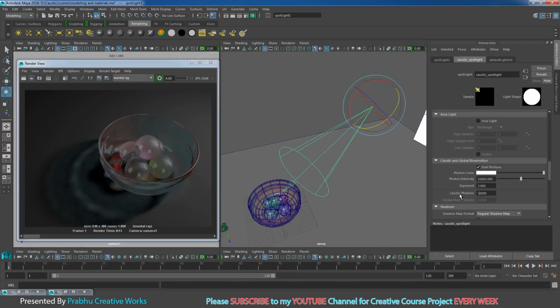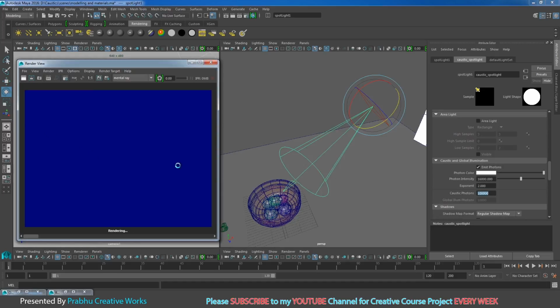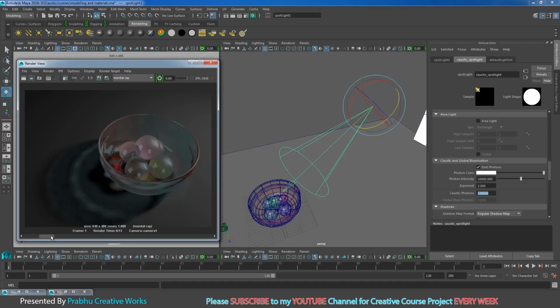So I will give 100,000 photons. I will keep this image for comparison and click render again. Now see it is much cleaner compared to the previous frame. So I will give 500,000 caustic photons, keep this image for comparison and click render. Now see, this is what we expect. The caustic patterns now split in a very accurate position. This is what we need.